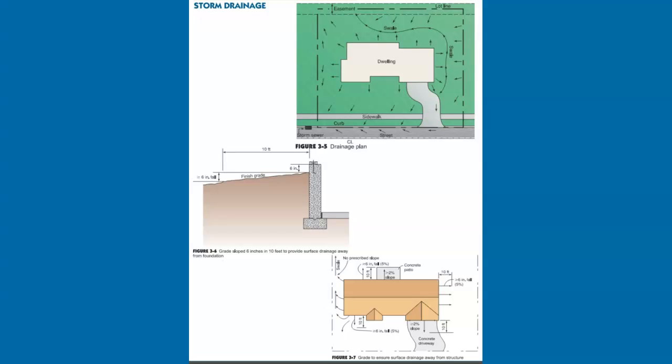Department policy for verifying proper surface drainage on properties will likely vary depending on geographic location, permeability of soils, and local history of damage and nuisances created by inadequate drainage. The building official is authorized to require submittal documentation sufficient to demonstrate compliance with the code. If deemed necessary, this may entail a detailed drainage plan with existing and proposed topographic contours, elevations, points of discharge, and any containment features. The building official may require that a registered design professional prepare such drainage plans.